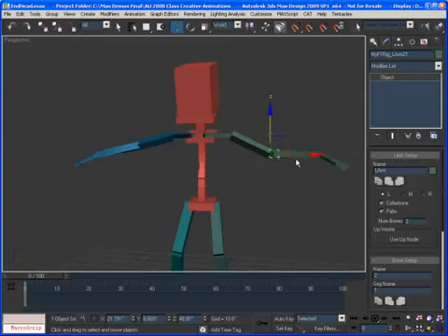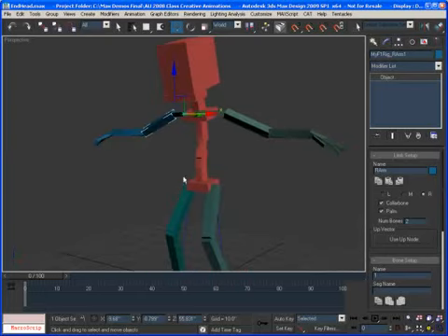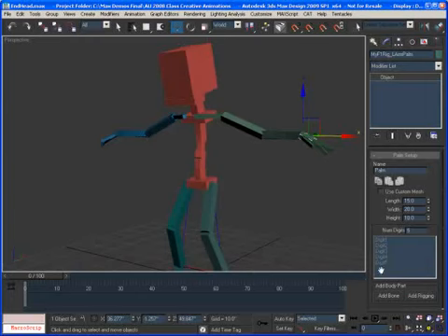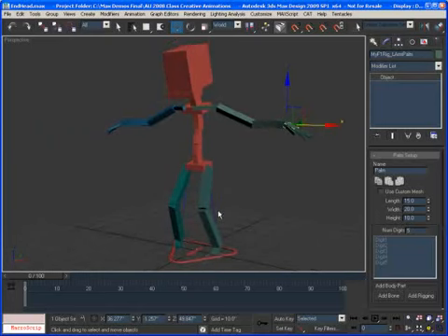If I grab this and move it up or down to change it dramatically, at least so that it's visible, I can copy this, grab any bone in the other group here and say paste, and it's going to paste the whole group structure onto the other group. By defining all of these things this way, especially on the palm with the digits, you'll be able to create poses for the hand, you'll be able to curl the hand with some sliders, and it's all provided by CAT automatically in animation mode. So that's pretty useful and pretty cool.